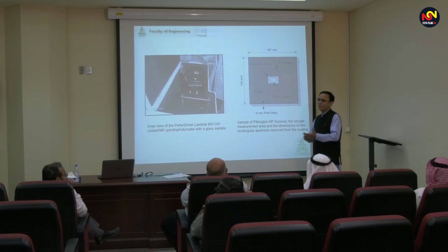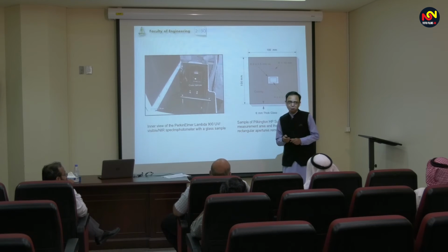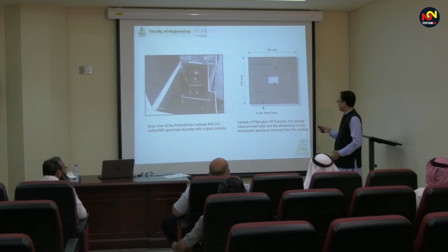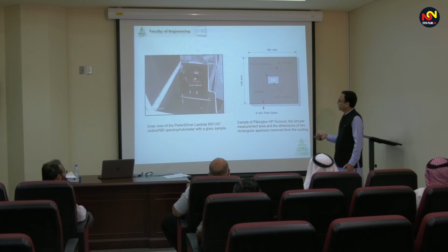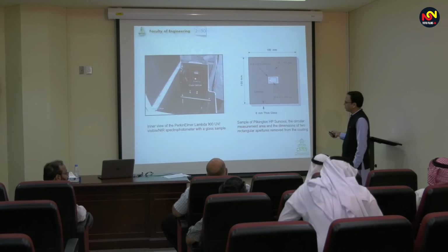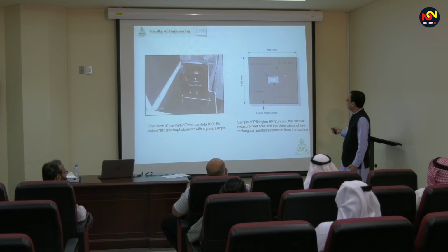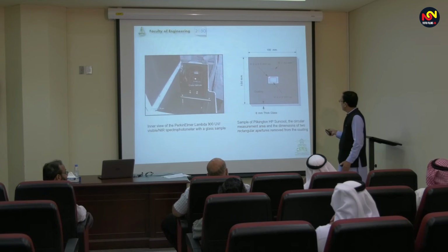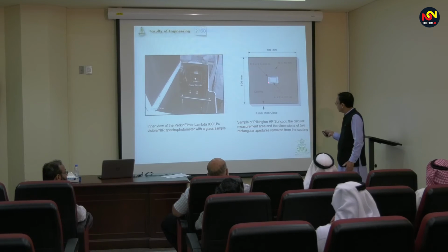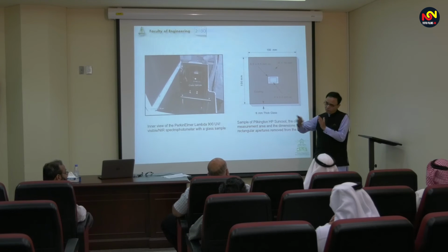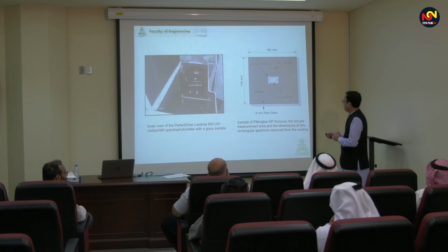How can I measure how much loss happened because of my aperture? So I came up with another solution. I asked them to give me a glass of this size with a coating. Then I first measured with the whole glass with the coating and saw how it affects. Then I took this area out and saw what happens. Then I took a little bit more area out to see how the amount of area removed is related to the amount of heat loss. And we came up with this.